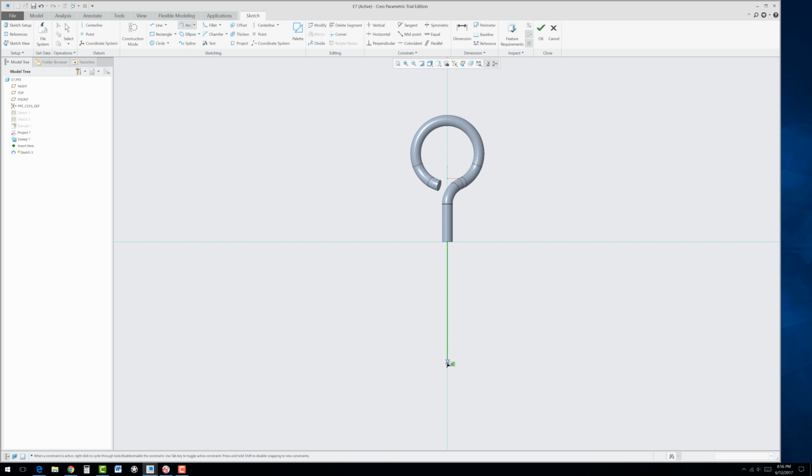And right here, click and drag this down. Don't go straight across to the left. Drag it down and hook it just a little bit like that. Click and middle click a couple times. Change the radius to 1 inch. Change the length to 7. And finally, let's use that little trick again with the center line, endpoint to center point, middle click. And look at that, I actually got it right the first time.